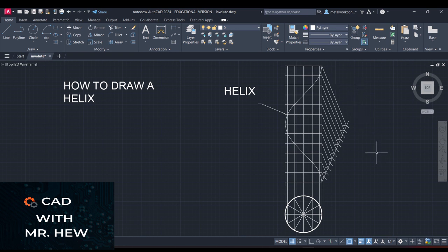All right. Now the helix, the section going beyond 7 is normally drawn in hidden detail lines, okay? So what we're gonna do now, we're gonna represent the hidden detail line on our cylinder, okay?